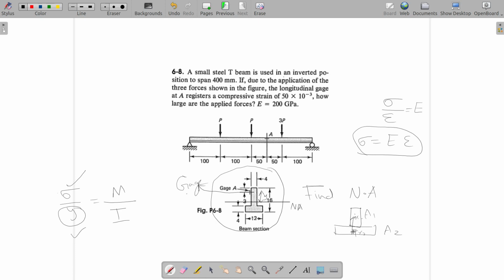So you have two rectangles here. You can calculate the moment of inertia of these rectangles about its geometrical centroid using the regular formula bd³/12, and once you have them, you can calculate the moment of inertia of these areas about neutral axis, and then add them up. So once you add them up, you will get total I.